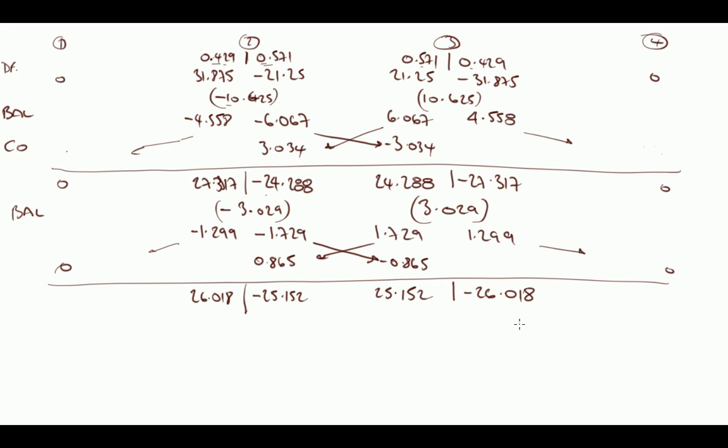So I am now starting to converge. Each time I iterate, I'm getting closer to a balance between this side of the joint and this side of the joint, and similarly this side of the joint and this side of the joint.